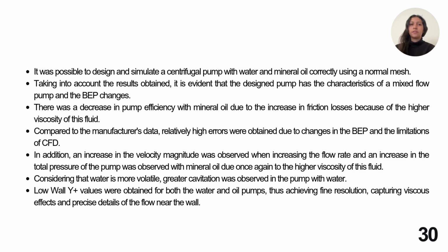In addition, an increase in the velocity magnitudes was observed when increasing the flow rates, and an increase in the total pressure of the pump was observed with the mineral oil, once again due to its higher viscosity. Considering that water is more volatile, greater cavitation was observed in the pump with water. And finally, low wall Y plus values were obtained for both the water and oil pumps, thus achieving fine resolution, capturing viscous effects, and precise details on the flow near the wall.